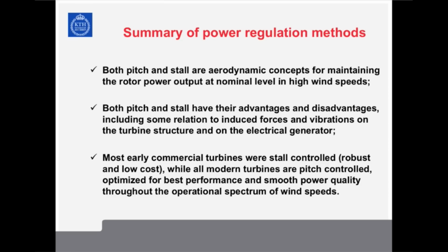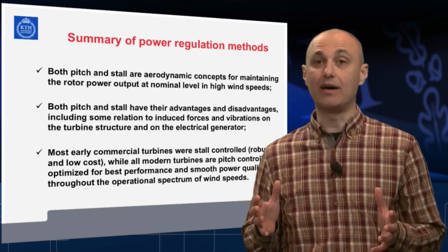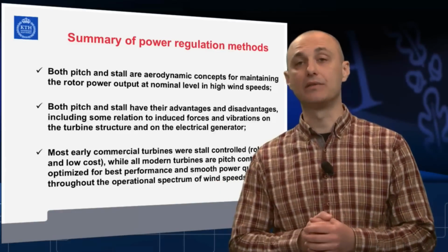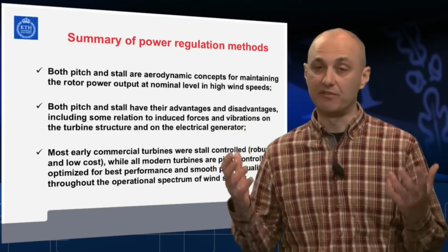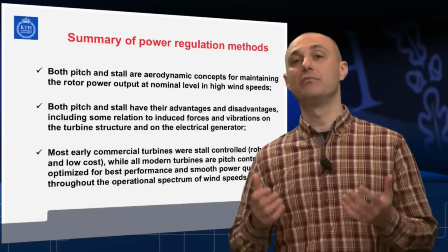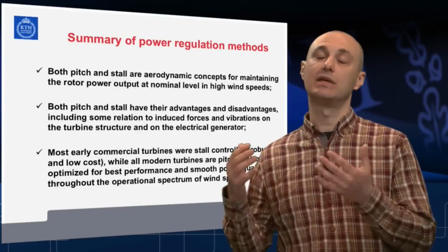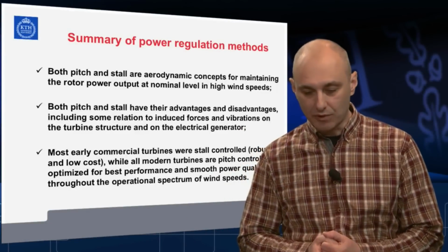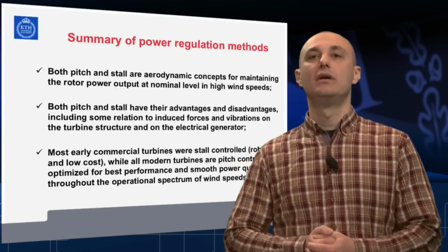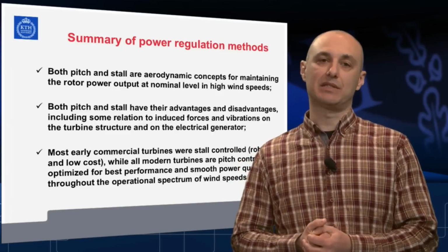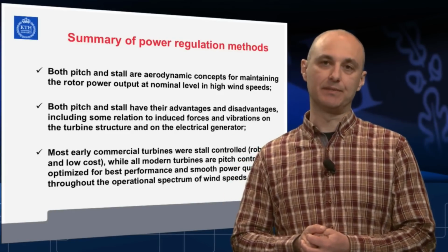Almost all modern big, large machines are pitch controlled. We need pitch now to be able to properly regulate the rotor, to be performing at the optimum level, both at low wind speeds, high wind speeds, and of course, to deliver maximum performance for the investment.